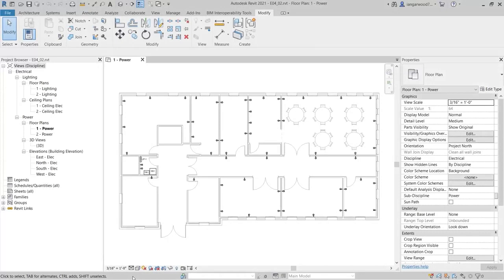In addition to ensuring adequate space for electrical equipment in a layout, provision must also be made to ensure there is sufficient clearance around each piece of equipment for access. To achieve this, we will work in the Family Editor to incorporate a three-dimensional volume to an existing piece of electrical equipment. This will include working with reference planes, dimensions and constraints to ensure the stability of the geometry.